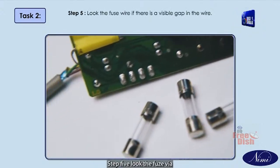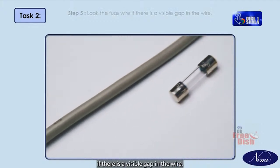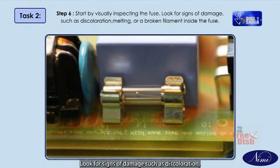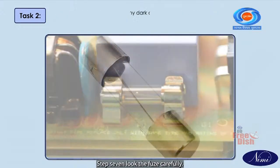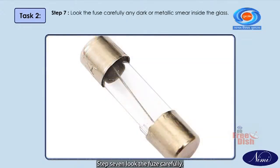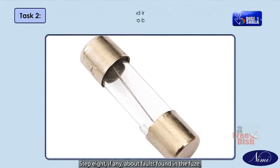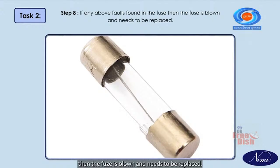Step 5. Look at the fuse wire to see if there is a visible gap in the wire. Step 6. Start by visually inspecting the fuse. Look for signs of damage such as discoloration, melting, or a broken filament inside the fuse. Step 7. Look at the fuse carefully for any dark or metallic smear inside the glass. Step 8. If any of the above faults are found in the fuse, then the fuse is blown and needs to be replaced.